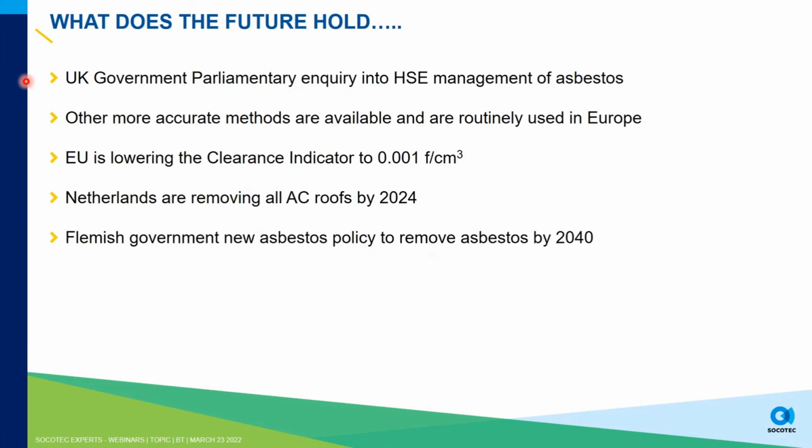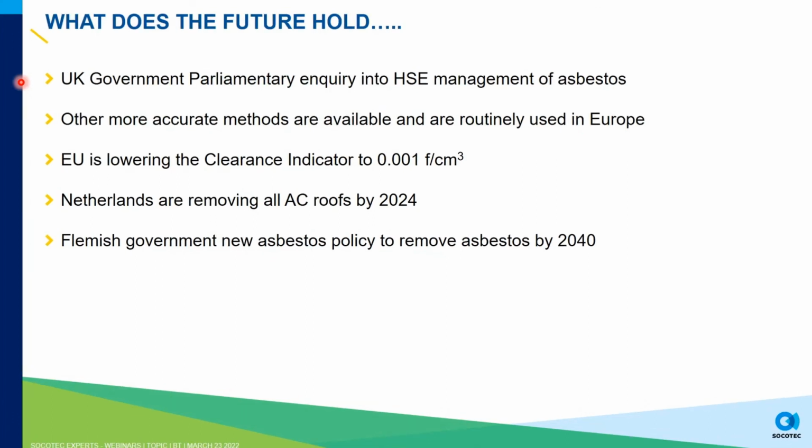But buildings are getting older. The ACMs in these buildings have been in place for probably 50 plus years. So AIB, lagging, etc., has been in place about 50 plus years, and is starting to approach its end of lifespan. Asbestos materials will deteriorate in the coming years. There's no planned phased removal in the UK. Therefore, is now the time to approach air monitoring to support ongoing asbestos management, perhaps moving away from the standard 0.01 fibres per ml clearance indicator test to a lower level, for ongoing reassurance over the next 10, 20, 30 years to demonstrate best practice in terms of asbestos management.